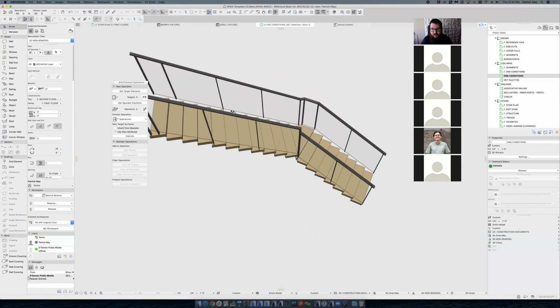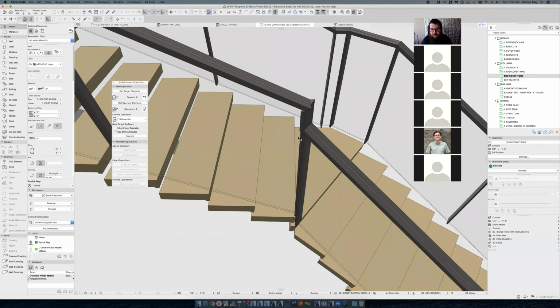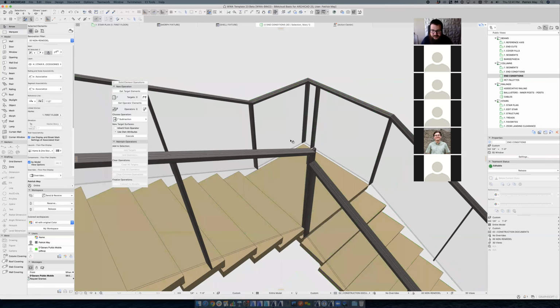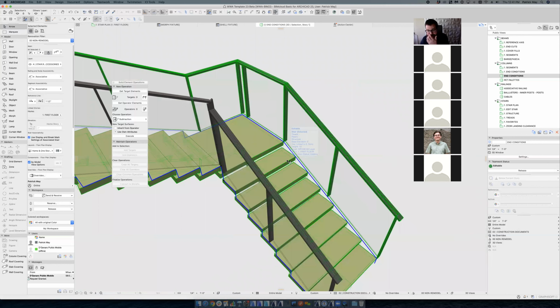Again, though, the railing tool is kind of goofy and clunky. You get stuff like this all the time with the railing tool where it's obviously not what we wanted. Even this is not what we wanted on that railing. So a lot of times with the railing tool, it ends up being just more efficient to model with beams and columns and an occasional morph or shell element.